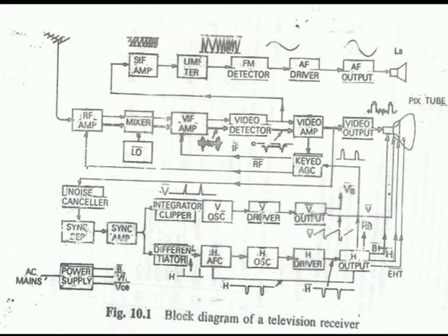It matches the antenna with the TV receiver, because ghost images can be removed. Whenever we match the antenna with the TV receiver, whatever extra noise or ghost image there is gets removed. It converts the RF signal into the IF signal by heterodyning with the local oscillator frequency. This RF tuner isolates the local oscillator signal from the antenna, preventing its radiation through the antenna.